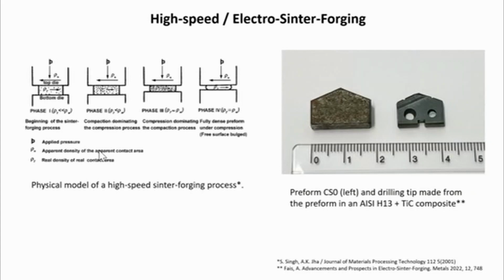The effect of this superposition when acting on metal or composite powders can be near full to full consolidation, even when the two synchronized processes last, in all the results described, only 20 to 30 milliseconds. The method is carried out in air, as no advantage has been observed thus far using vacuum or argon as a protective medium during consolidation.